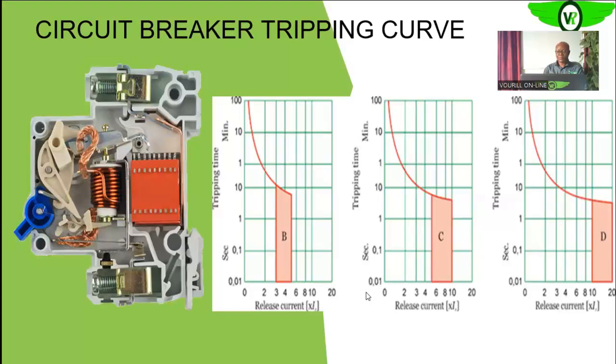So you need to know this when selecting your circuit breaker, because each of these tripping curves affects the operation of the circuit breaker, and each has different areas of application where it will be effective. What do I mean? Let's assume that you select a circuit breaker operating within a B curve for a very high inductive load, maybe a motor load, or as the input to a high power transformer.